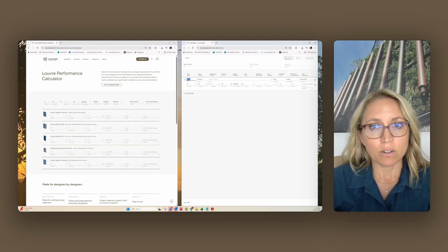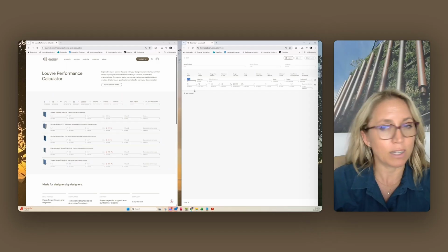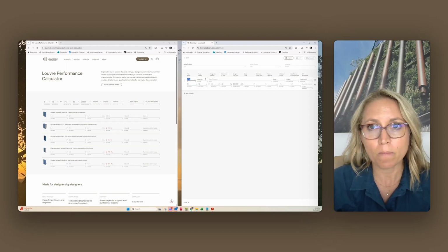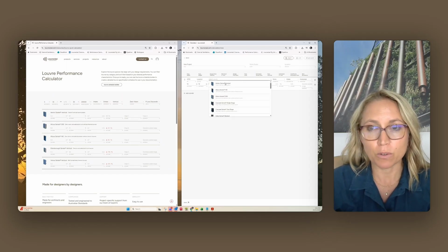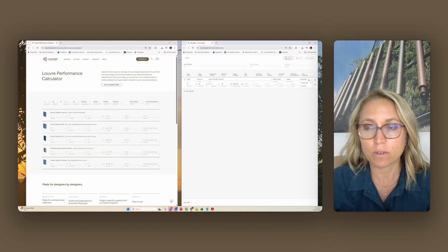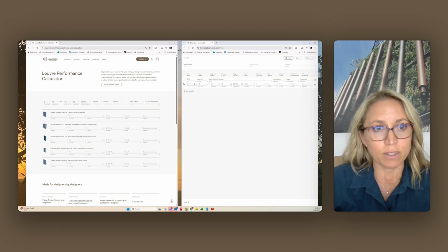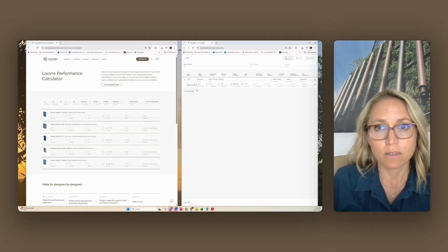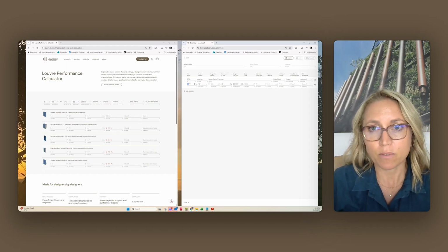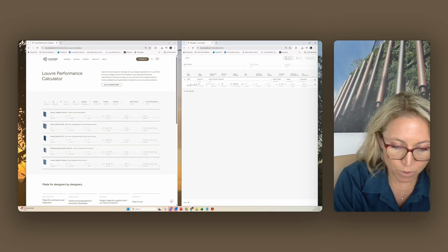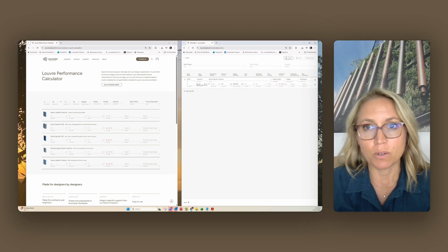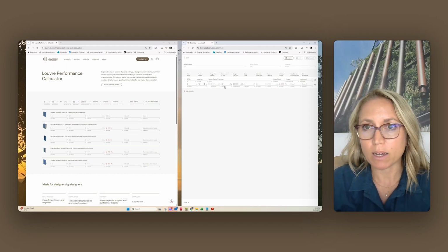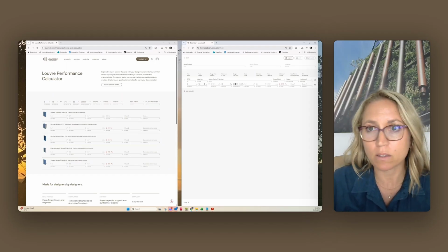To start, you can enter a reference for your louver so that you can easily reference it back to the drawing that you're working on, a location, elevation, etc. You then manually select the louver that you're working with, any accessories, intake or exhaust, and the louver size that we've worked out from the selection tool. You do have to enter that manually once more, I'm afraid.